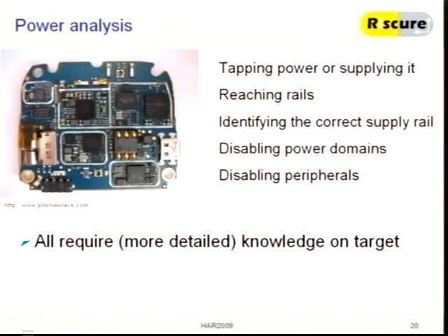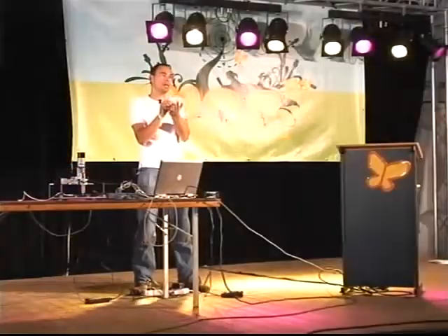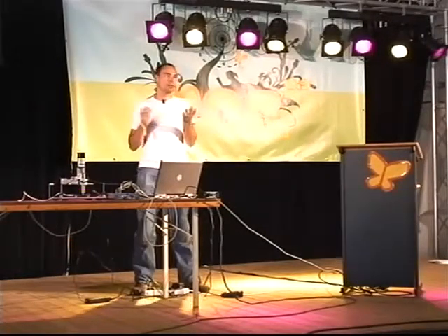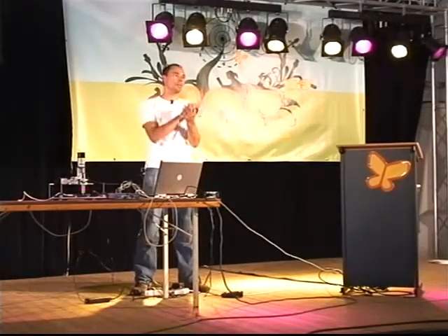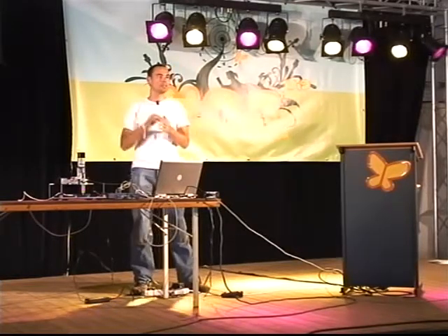Well, that's often not the way it's implemented. The idea is if there are a lot of decoupling capacitors on the board, that you can use them to do your measurement. Actually, the point is that most of the time you want to get rid of all the capacitors because they flatten out your power profile. So it's more the opposite.